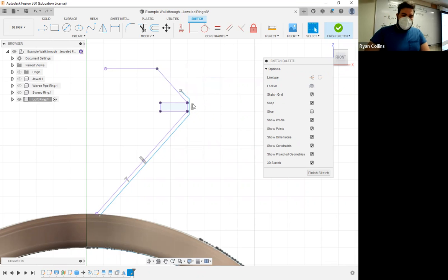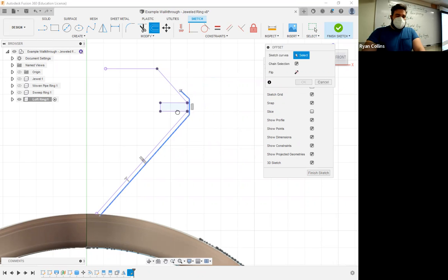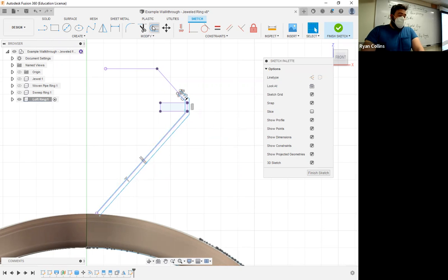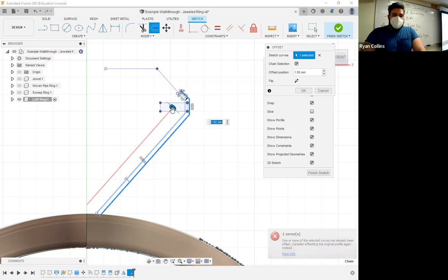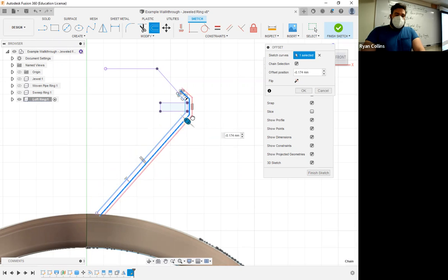Delete those. So realistically, what I'm going to need to do now is use an offset line, and I probably should have actually had it intersect the actual drawing a little bit. Okay, I'll go something like that. Sure, 0.2. Let's go 0.3 or 0.25, something like that. Sure. Intersection. I'm going to do another one because I'm just drawing a line that seemed about right. And this one's going to go on the outside, or better yet, hit escape, and let's offset the offset just to be extra confusing. Oh, right, you can't offset an offset.